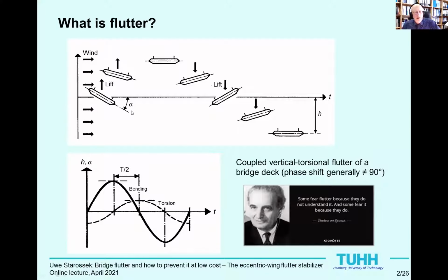This means that the vertical lift force is in phase with the vertical velocity, and this actually at any time during a vibration cycle. A force in phase with velocity, however, corresponds to negative damping, meaning that energy is fed into the system to the effect that the vibration continues with the same amplitude or even increases in amplitude.